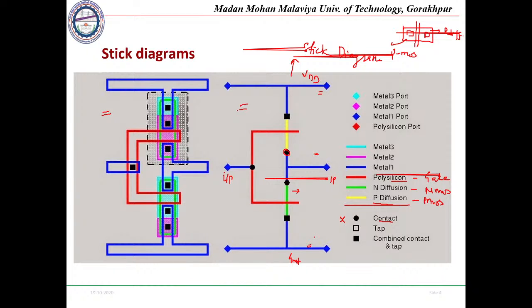It will make it easy. With this placement and designing, we reduce the number of interconnects when using different components. We are connecting different components, so we should be minimizing the number of interconnects. If these interconnects are minimal, there will be fewer parasitic capacitances, so it will not affect the actual physical circuit and its other parameters. Once there are more parasitic capacitances, the output will change.